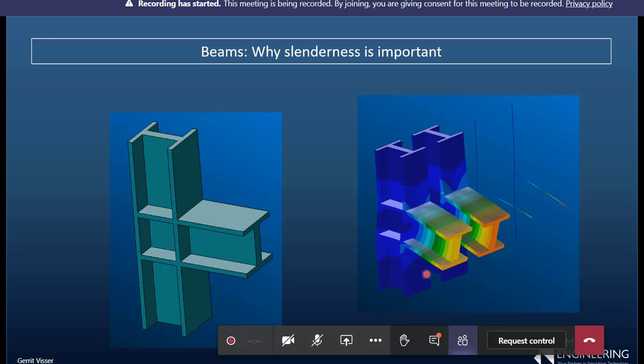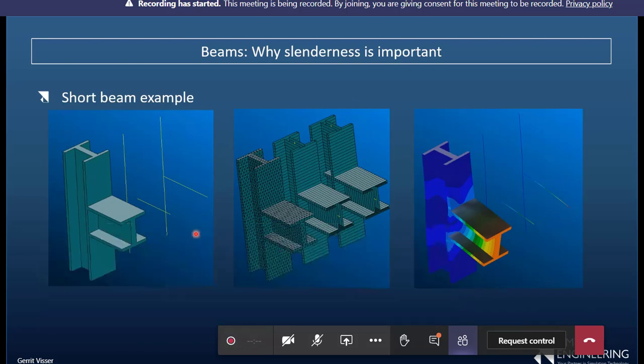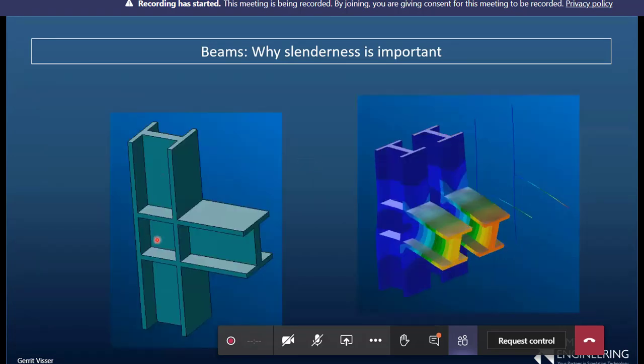Okay, now how would I model this with a beam section? Well, one way would be to extend that to the center. What do I do with that little bit at the back? Unfortunately it doesn't show there at the back. You can see that little bit of penetration, but there's stuff kind of missing at the back. I'll probably model this very similar to the way you'd model that one, where that I-beam is welded on but without stiffness. But in reality, it's a significantly different model.